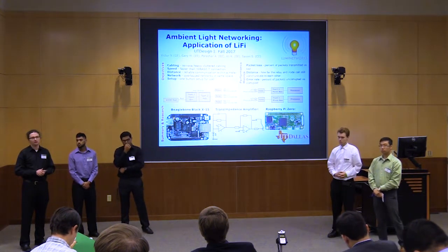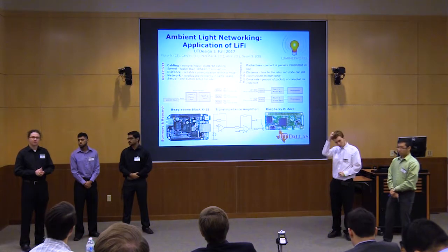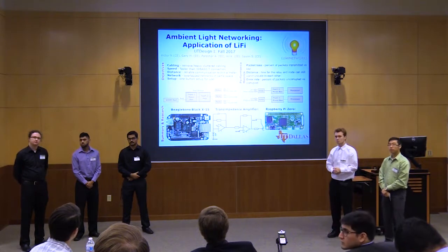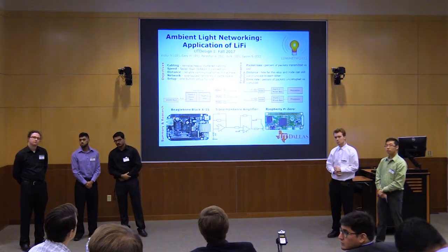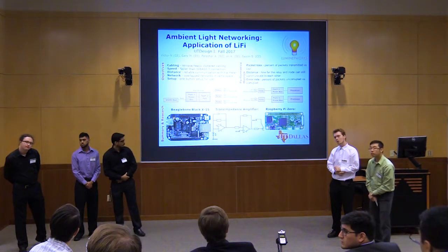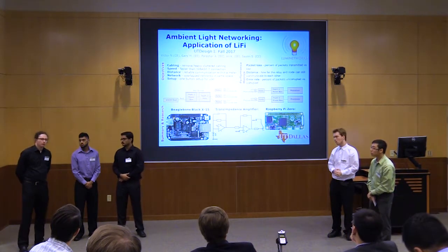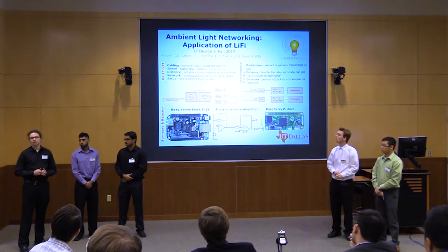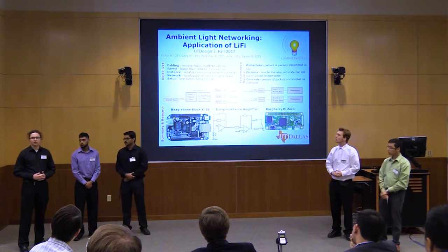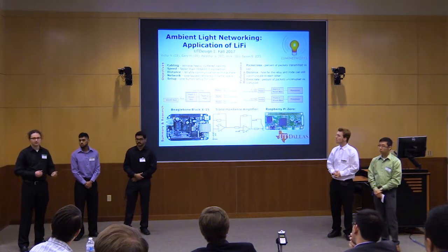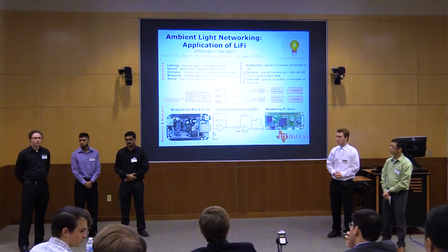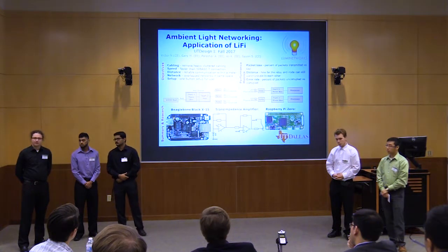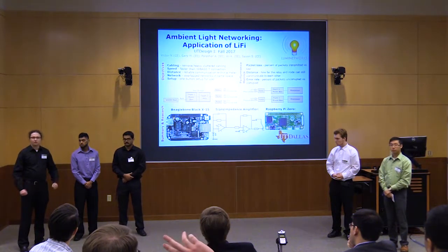The other thing is that we're trying to get it where it has about 20 megahertz of bandwidth, so that it can handle. So what is the problem if you want 20 megahertz bandwidth? What is the problem if you want to have 20 megahertz bandwidth? Well, the thing is that for a particular amplifier chip, there's a trade-off between the gain, or sensitivity, and the bandwidth. We're having to carefully choose the right chip that can give us that performance.